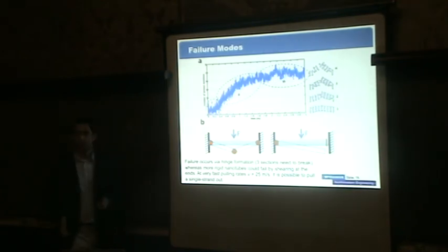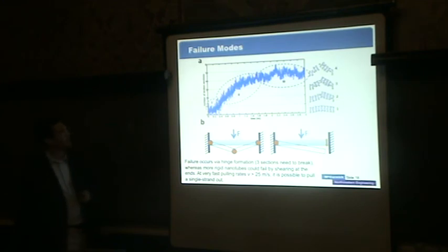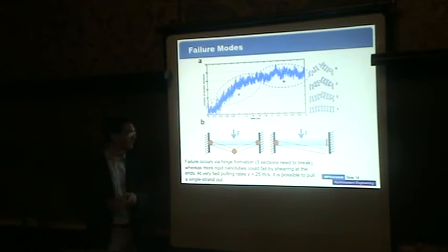And then when we look at the deformation, we can do some very simple analyses. What we observe is basically failure typically occurs in what looks like a hinge formation. So instead of just shearing the system, you need to break it at 3 different points, which basically forms 2 hinges and then the central point, which leads to stability. So an alternative mechanism, if you had a very stiff nanotube, would be localized failure on one or the other side due to some heterogeneity, or localized failure at the central strand which you are pulling on. And that can be observed.